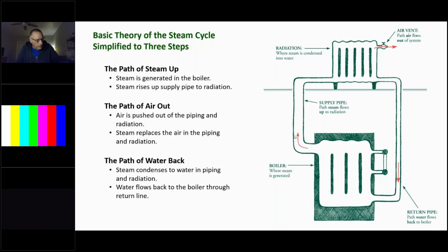There's a way to check whether you've got oil in your water. You'll need an old pot that you're never going to use in your house again. You drain a little water off the boiler drain, put it on the stove, and heat it up to boiling. With a standard pot of water, you notice that steam gently wafts off the top of the water.